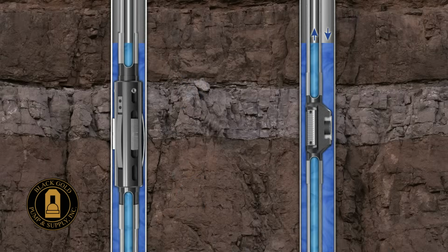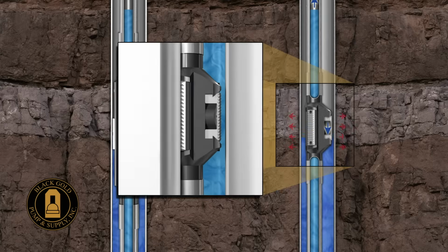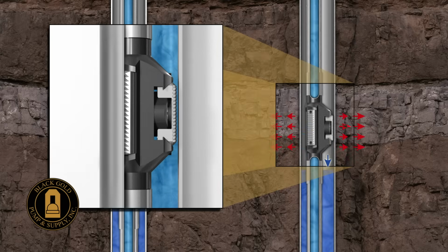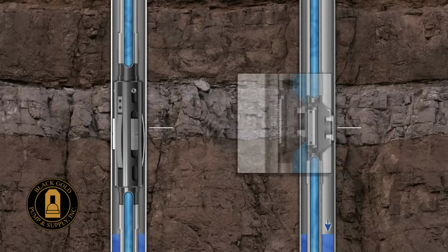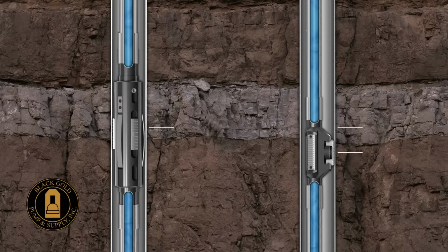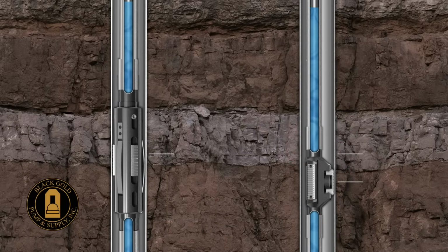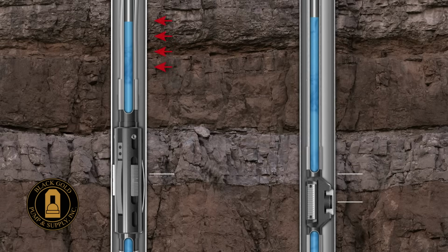As the fluid in the well is pumped up to surface, the fluid level in the casing will slowly lower to the pump. As this fluid lowers in the casing, the pressure inside the tubing increases due to the increased differential pressure. This load on the tubing causes it to stretch downward. The hydraulic anchor accommodates this optimal tubing movement and prevents the tubing from going into compression above the pump, as can be the case with an improperly set mechanical anchor.